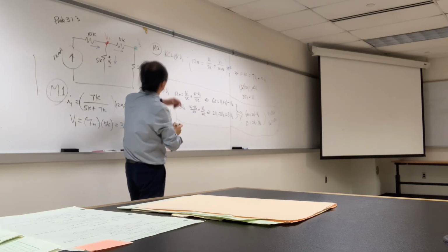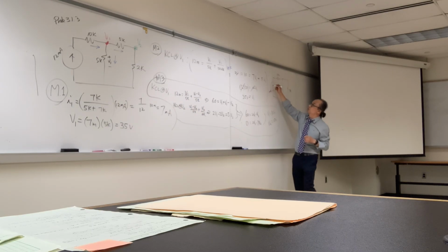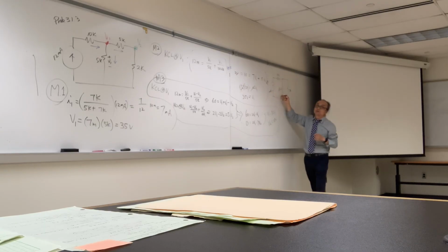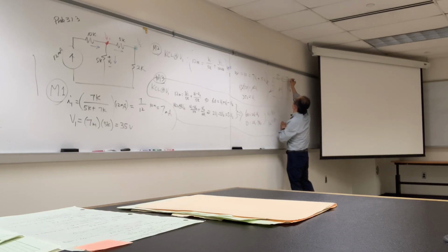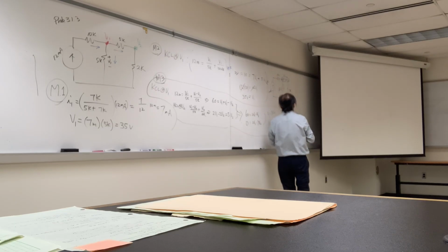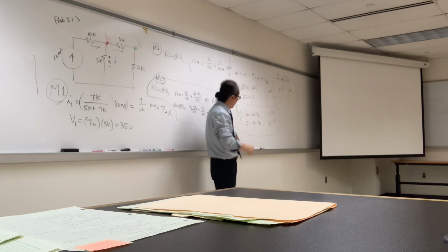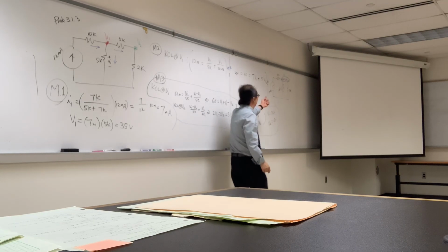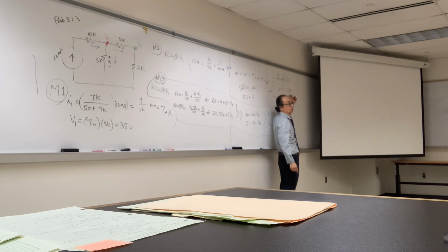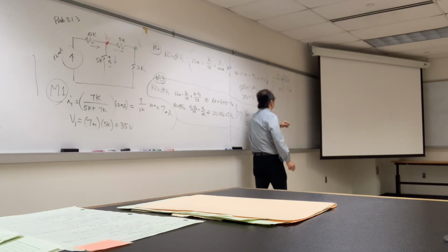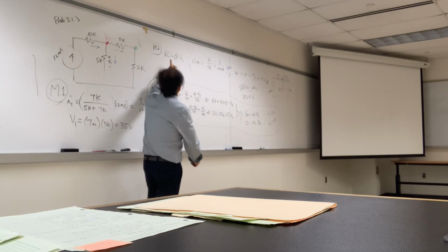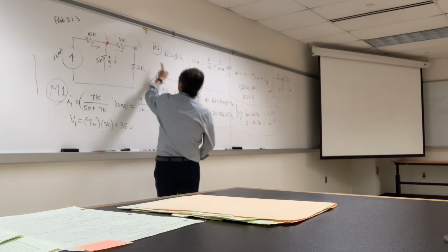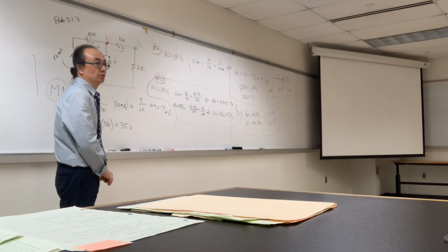So your question is about method 2? For method 2, I use this circuit. Therefore, this whole node is going to be V1 plus, this is V1 minus. The voltage across the 5 kilo ohm resistor should be the same as the voltage across the 7 kilo ohms, right? So these two are in parallel. They share the top node and bottom node. So in this case, we just need V1 only. But for this one, we have V1 and V2.